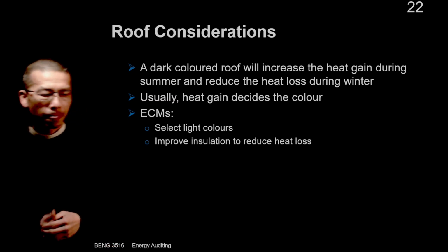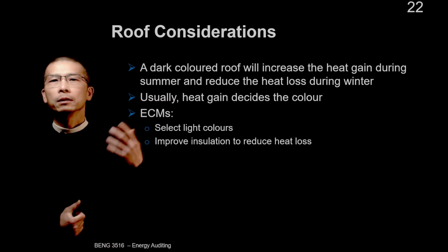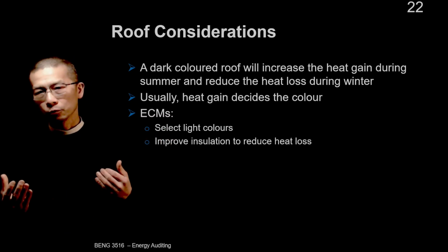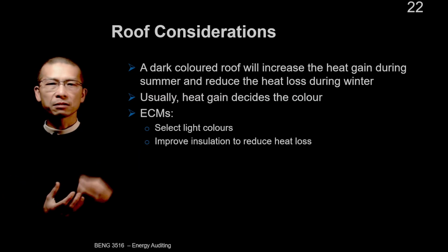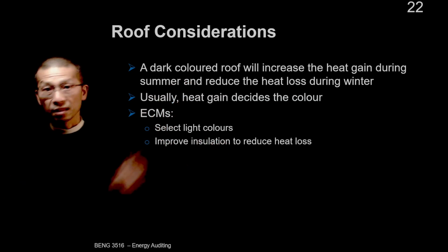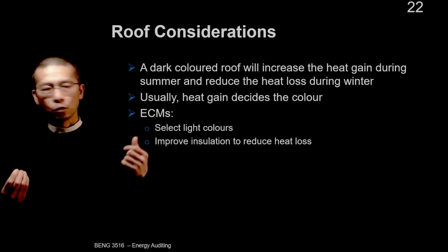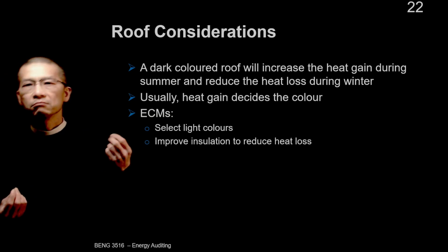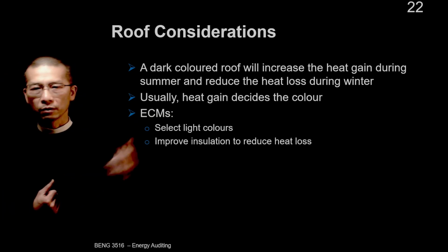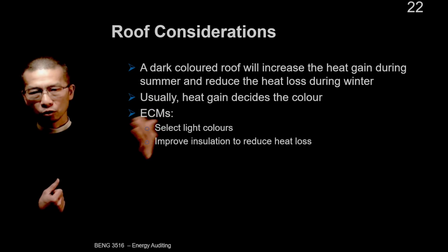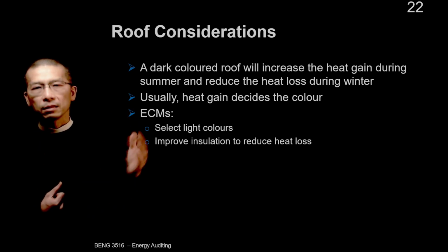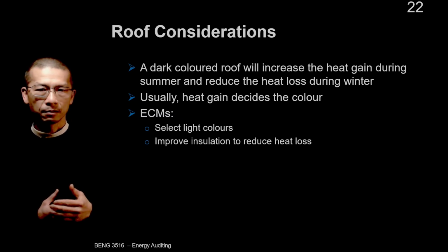Okay. Roof. So for the roof, we have to look at the balance equations we discussed earlier. A roof is typically the largest surface area exposed to the sun, making it critical for the solar heat gain. So we look at the color. Again, dark color absorbs heat, light will reflect. So for cooling load, it's the deciding factor. Therefore, we prioritize the strategy that tries to eliminate that summer heat gain. Okay, summer heat gain.